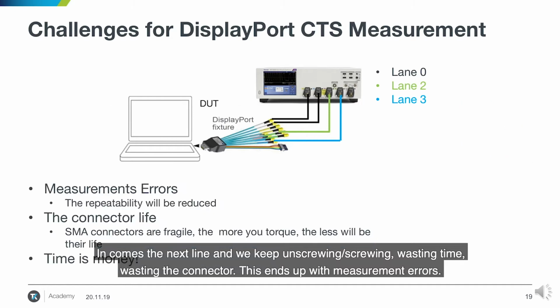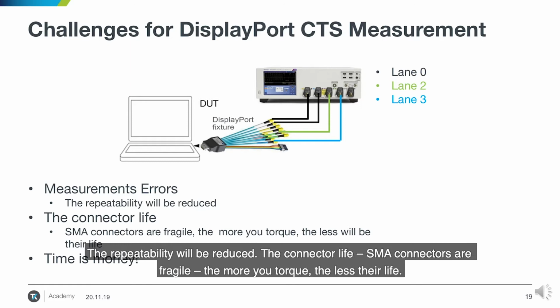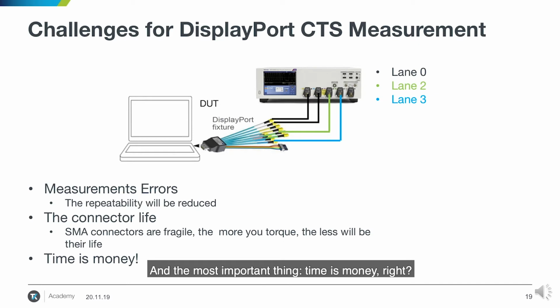This ends up in measurement errors. The repeatability will be reduced. The connector life: SMA connectors are fragile. The more you torque, the less will be their life. And the most important thing, time is money, right?